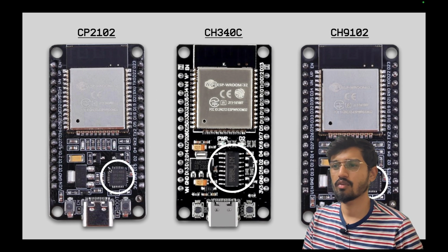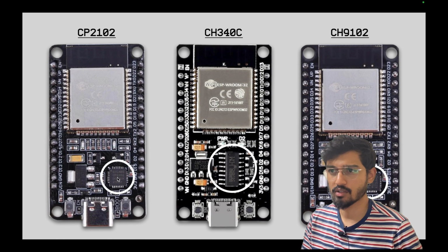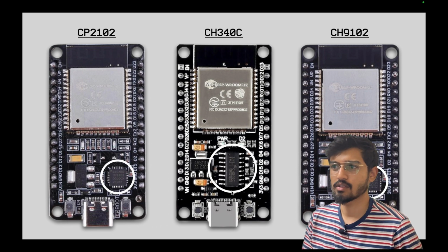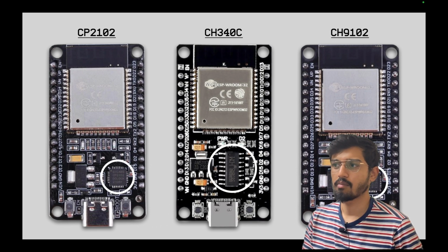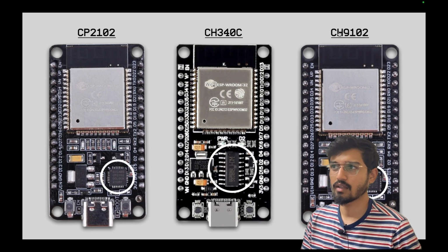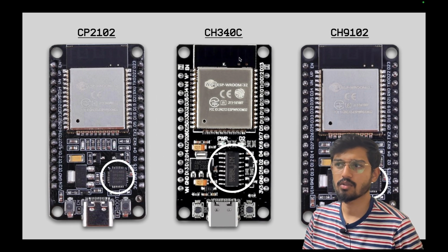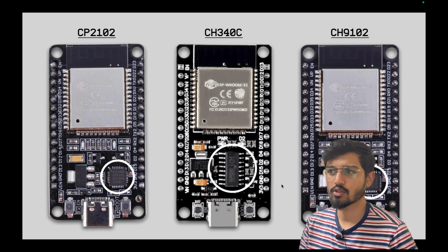And if you flash some light on the chip and try reading the part number, you will see that 99% of the times it is CP2102. And if you have this longer version of the chip, then it's definitely CH340C, but very rarely you will find that it is CH9102. So depending on the chip you have, you need to install the drivers.